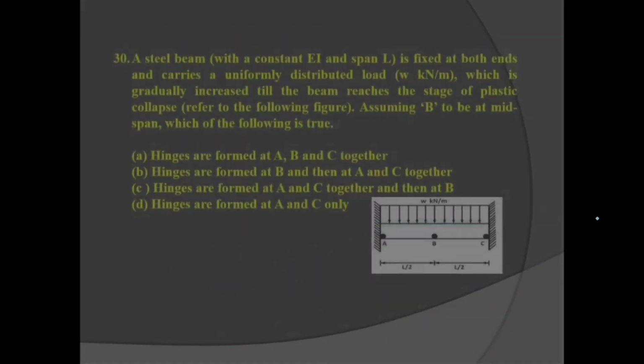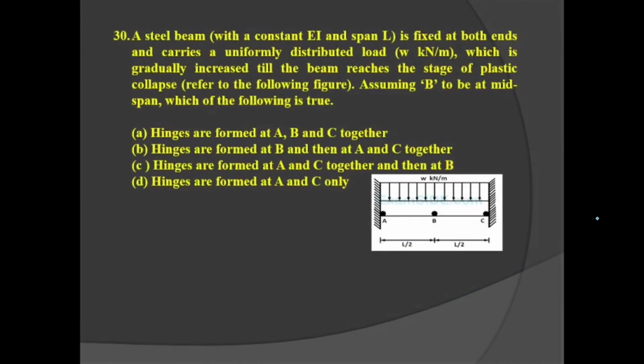Question number 30. Fixed beam subjected to UDL over entire length. Obviously, bending moment at supports is always more than the bending moment at center. So bending moment at supports must always be more than bending moment at center. Therefore, option number C is correct.